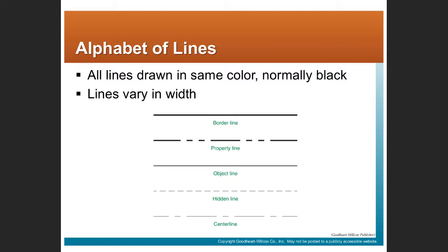And this long, short is a center line, right? I think one of you asked a couple weeks ago, are we always dimensioning to the center of a door or window? And I think I answered yes, but I should have looked at the style of line to make sure that line had the characteristic of an extension of a center line.